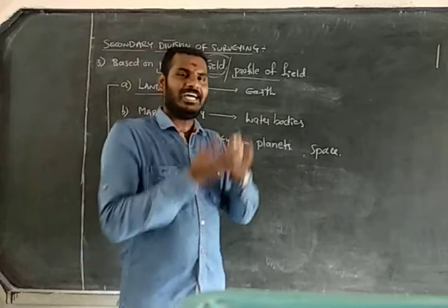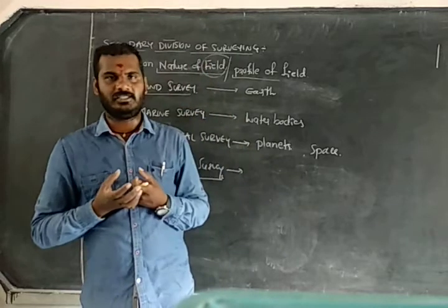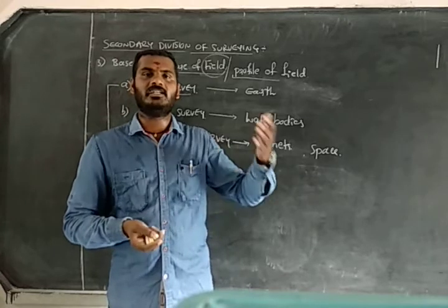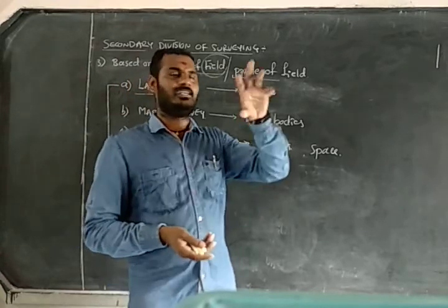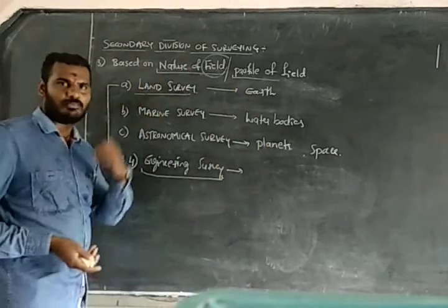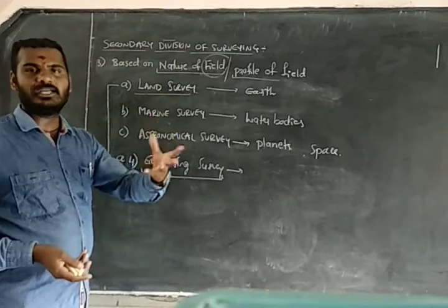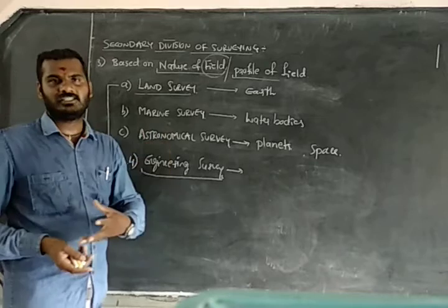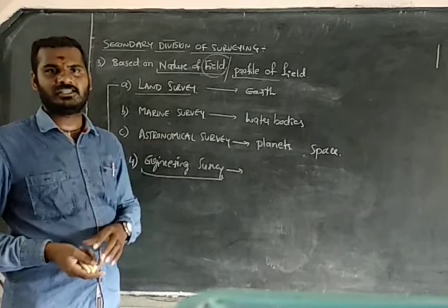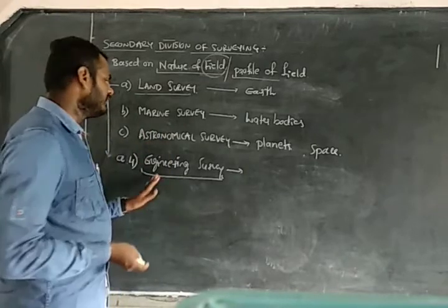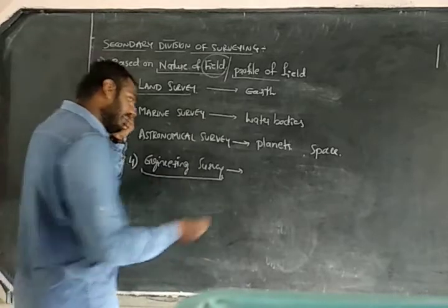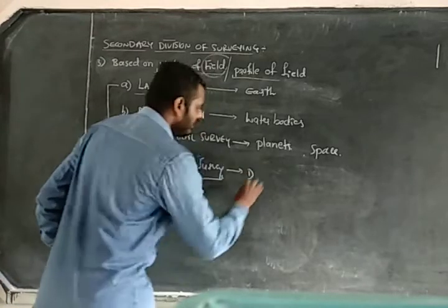So, acquiring detailed knowledge regarding a particular structure, or to establish a particular structure, the process that involves acquiring the data required to execute or construct a particular structure comes under engineering survey. It includes some stages. The first stage is reconnaissance.